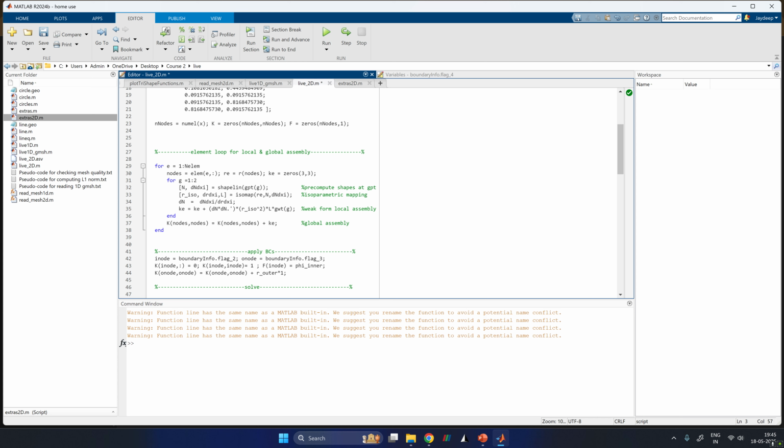We just have to make this Gauss rule equal to 6. These are our elemental y coordinates, and this will remain the same. Previously this was for quadratics, but even in the case of triangles we just have 3 points, so this will remain the same.